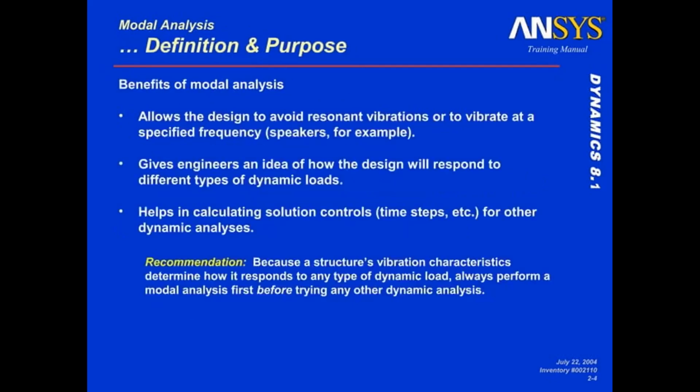The benefits of modal analysis: it allows the design to avoid resonant vibrations or to vibrate at a specified frequency. For example, speakers. It gives an engineer an idea of how the design will respond to different types of dynamic loads, and helps in calculating solution controls, time steps, etc. for other dynamic analyses.